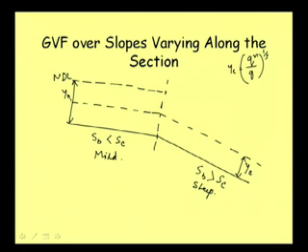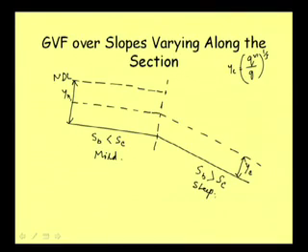But in this portion, in the second reach of the channel, here as it is steep slope, the normal depth line will be less than the critical depth line. So, it will be somewhere here. So, the normal depth line we are drawing here. This is say YN2.